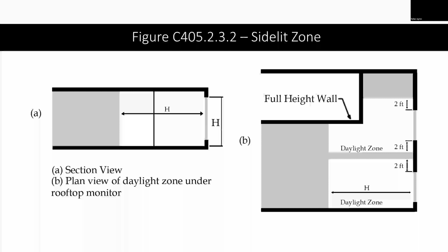Probably a better example is if we put a window here, and say it's a 7-foot high window sill height, then it goes 7 feet from the air and would double dip on its own, but in this area you still only count the area once. So what he's saying is those would have to be 2 separate daylight zones. Yes, so you can control them with the same sensor if they're part of the same correction, provided it's limited to the 150 watts.